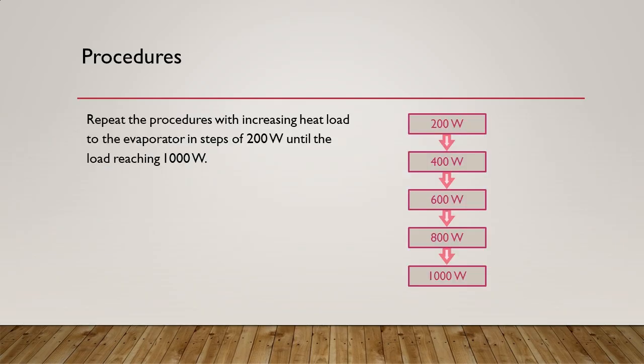As mentioned, repeat the procedures with increasing heat load to the evaporator in steps of 200 watt, until the load reaches 1000 watt. And remember to allow the unit to achieve steady operation after each step of load increment before taking your readings.